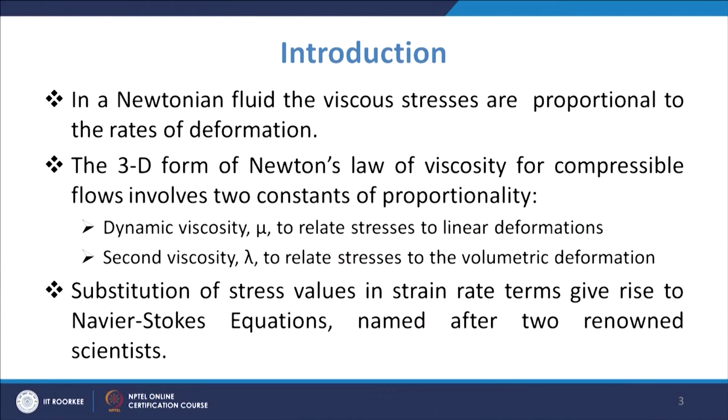Mu is known as the dynamic viscosity, which relates the stress to the linear deformation. That is what we have seen in the case of Newton's law of viscosity earlier. But in the case of compressible flow, you have a second term, that is the second viscosity, lambda.